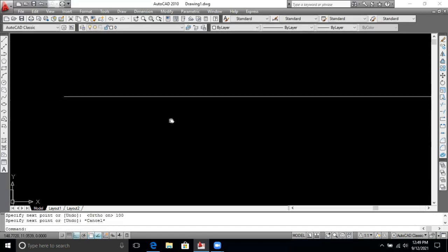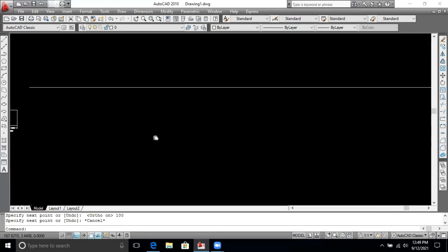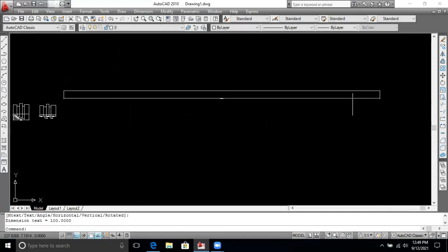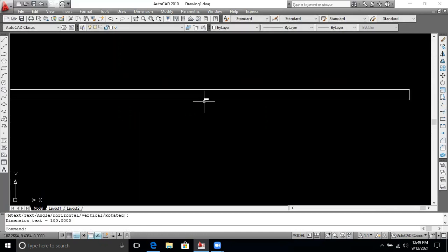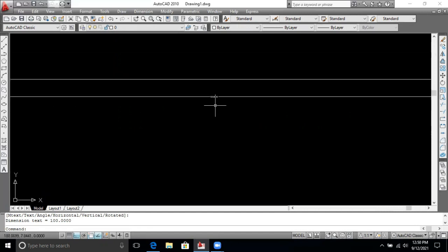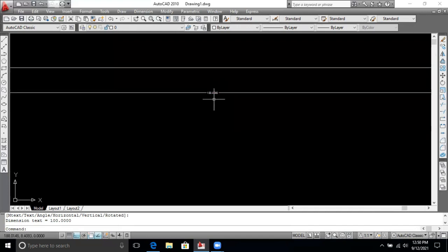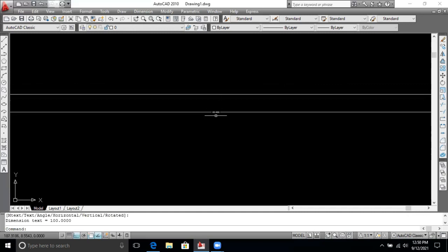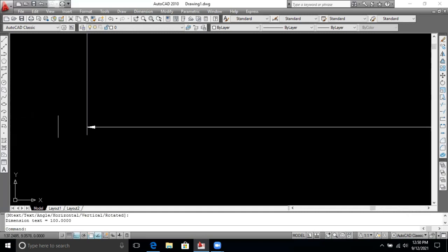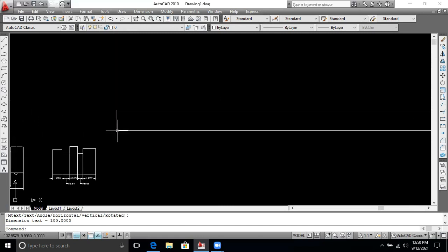If you dimension any lines or a circle or arc, this type of problem you have faced: the dimension text does not appear. Why? Because the dimension text height is too short. So how can we define the height and the size of this dimension arrow?